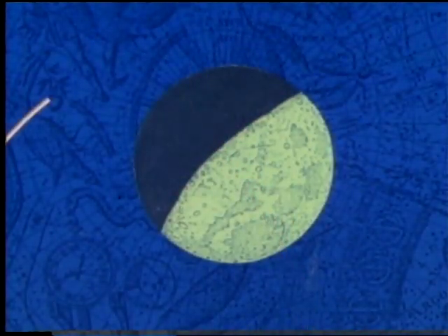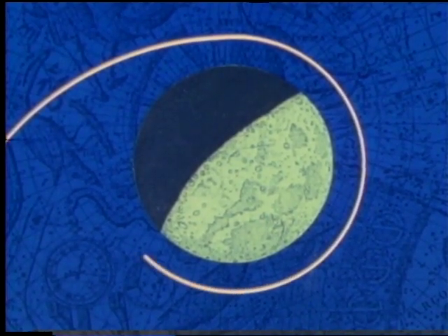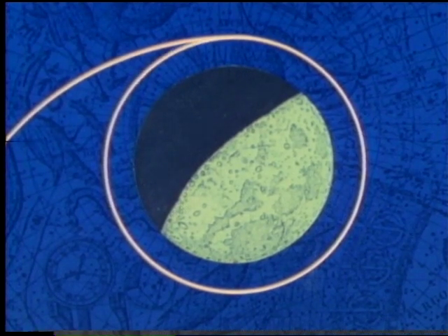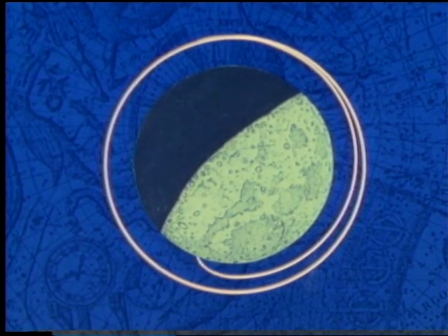Before presenting the actual entry of the Apollo command module into the atmosphere of Earth after its lunar expedition, we will review quickly the overall mission to this point. The Apollo space vehicle and its crew were placed in an Earth parking orbit, then injected on a trans-lunar trajectory. A burn of the service module propulsion system provided braking and a plane change that placed the spacecraft into the proper orbit for the lunar landing, the landing to be performed in the lunar module.